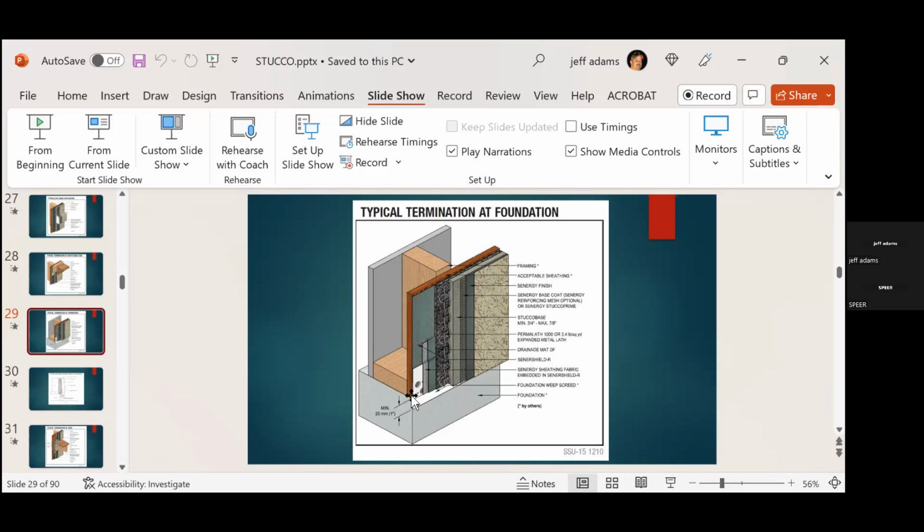So when it does that and you use the pre-punch nailing holes to secure it in the toe plate like you should, you're going to get roughly a 2 inch overhang. I mean, don't go around measuring and go, oh my God, this one's only 1 3/4. Depending on where the holes are at, nailing into your toe plate, or your sole plate, whatever you want to refer to it as, you're going to get some deviations. But if you're getting anything over 1.5 inches, they probably did what they were supposed to do here, okay?